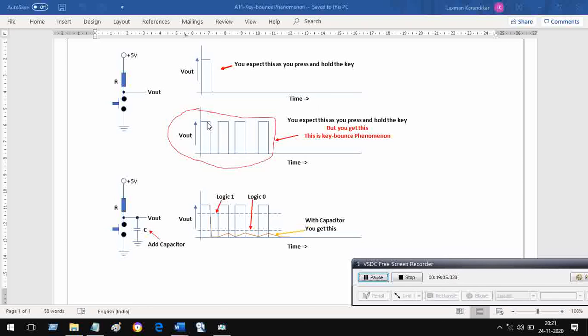That interrupt will occur when it goes from 1 to 0. It may occur when it goes from 1 to 0 and remains at 0. It will occur when it goes from 0 to 1 and remains at the top, that is, at logic 1. So all possibilities exist. You can select, you can choose. That is called configuring the interrupt of the IO port.